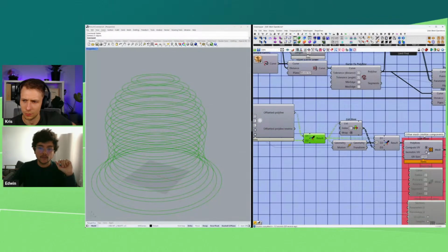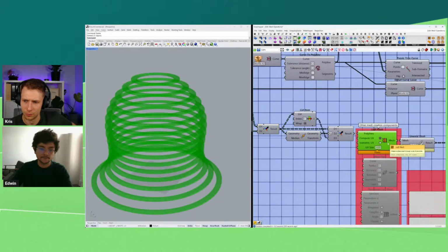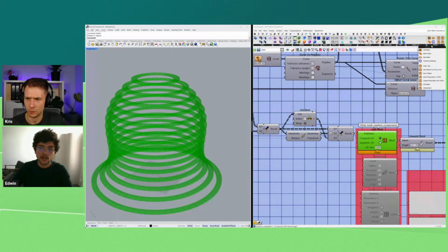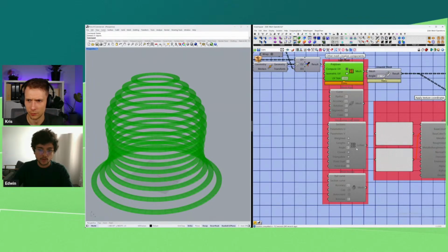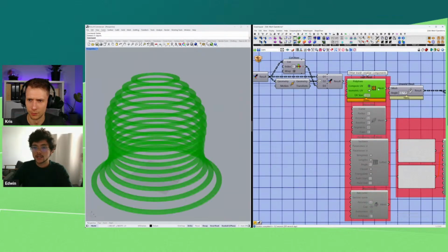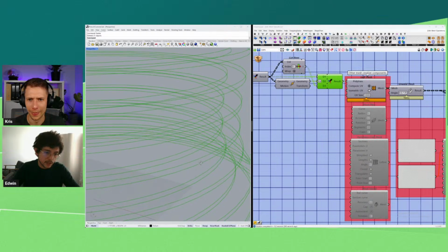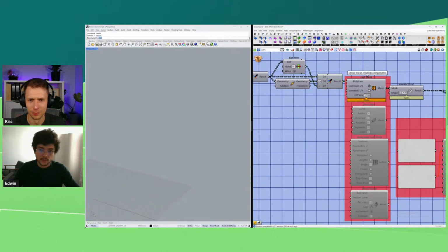So here, when I create the mesh, I do it with this component called the loft mesh component, which is also something from the utilities section in Shapediver. However, there are other components also in other plugins, especially Pufferfish: mesh pipe component, parameter loft mesh component, mesh sweep component. All of these come from Pufferfish. In this case, I'm using the loft mesh component, which needs to have the same amount of points because all it does is, I have here the wireframe and it's just connecting every single point. If I explode this.